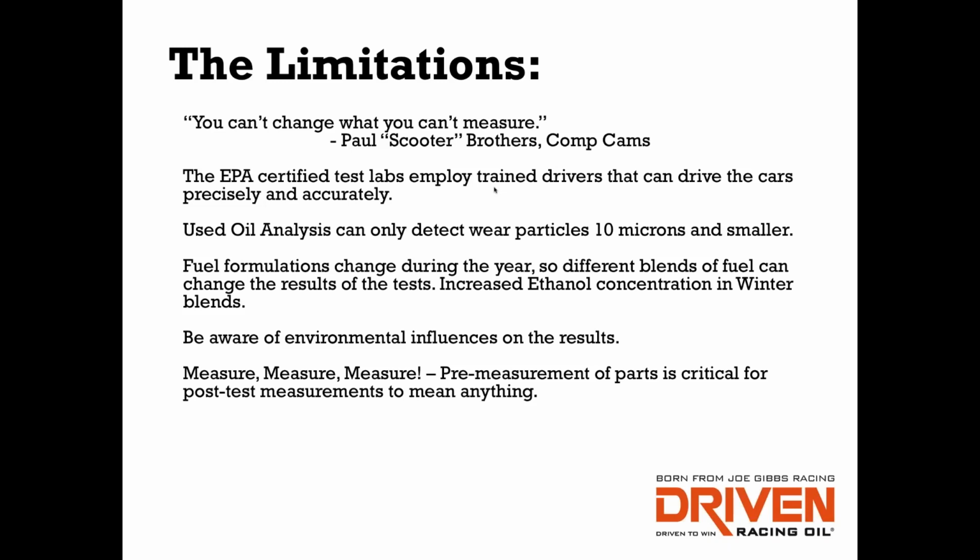It kind of goes to the point of, people may not know it, but when you go buy a car, it's got that little EPA sticker on the side that says it gets 28 miles per gallon city and 34 miles per gallon highway. There are drivers whose job is to drive the EPA test procedure. To get those city and highway numbers, there's a designated procedure that the driver must drive. They take cars that are already produced and drive them on a chassis dyno in a very specific manner. That's what they get paid to do.